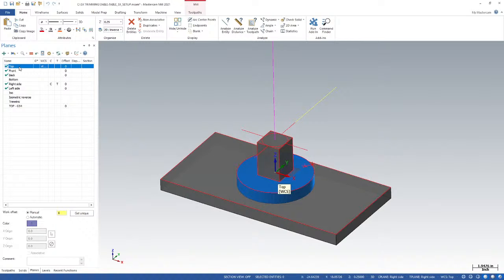Now the origin point can be a couple of things, right? On a 3-axis machine, we're talking about our work coordinate system, our work offset. Most machines these days use G54, G55, G56, and if they have an extended series of work offsets, you're using G54.1, P1 through P48, in some cases P1 through P99 or 100. It depends on the machine configuration as to how many individual work offsets you've got.